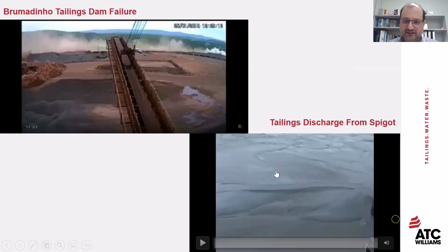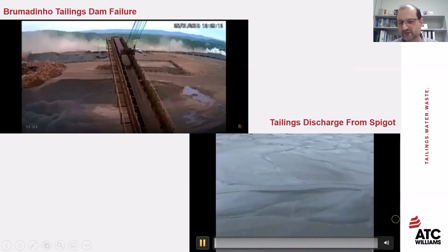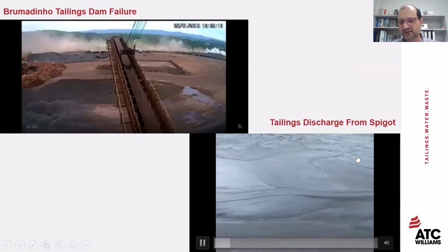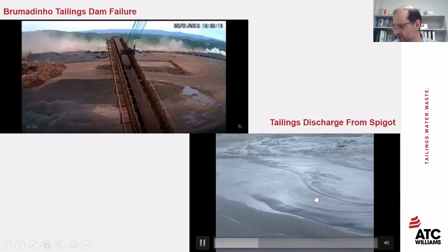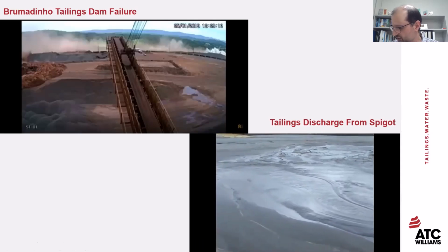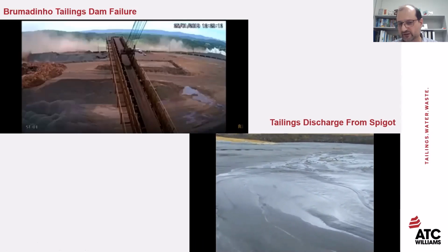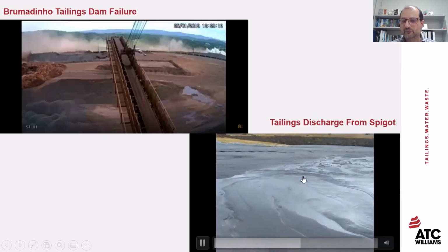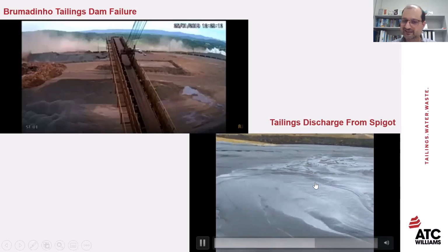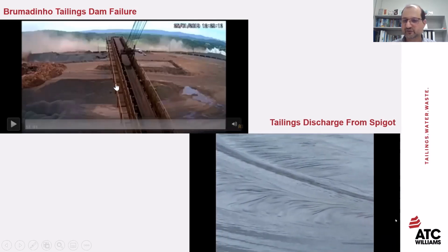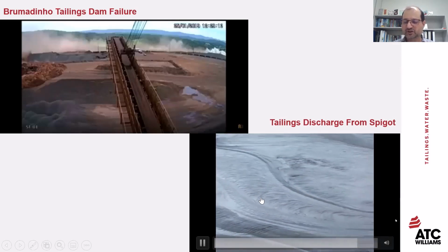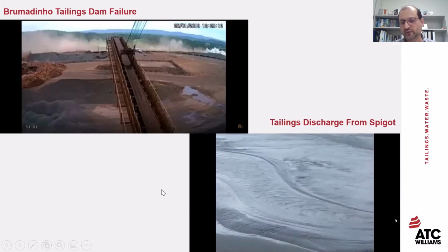Over the last 15 years, we have heavily invested in research and development of models to understand what you could observe in this video, which is the thickened tailings discharge on the beach and beach development. We have developed multiple models. We have sponsored 3 PhD research works, including my PhD research work, and we developed several published models on the open channel flow of non-Newtonian fluid, thickened tailings slurry, which is very similar to the release of slurries in the dam break scenario from a dam. The same mechanism, the same equation, the same fundamentals apply to both flows.